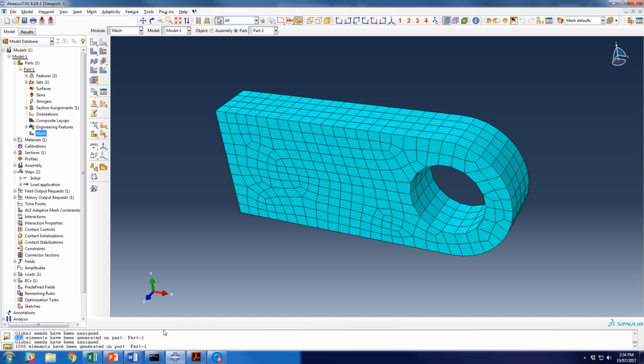This is obviously due to the fact that we have a 3-dimensional feature, so when we double the amount of elements, it's roughly going to be 2 cubed, because 2 is for half the element size, and cubed because we're working in 3 dimensions. 2 cubed is 8, so this is roughly 8 times the number of elements, roughly speaking. So that's sort of how that works.